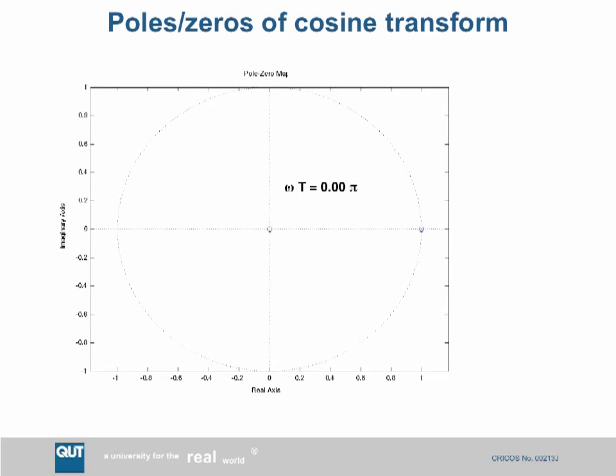I don't quite know what happens there at the end. Okay. So we have this ambiguity when omega t is greater than pi. Now this is really important. We call this effect aliasing. So there are frequencies, omega t, scaled frequencies, that are not unique. They're unique up to pi. Beyond pi, they get wrapped back and appear the same as frequencies that are in the range 0 to pi.